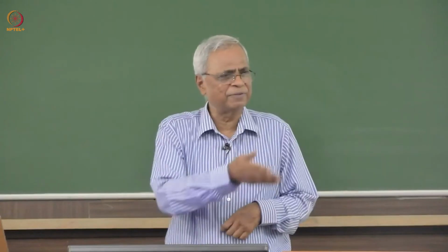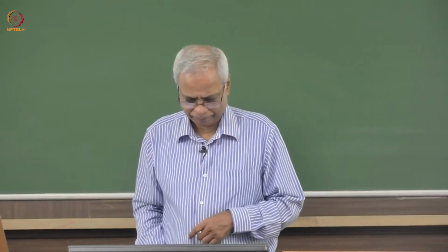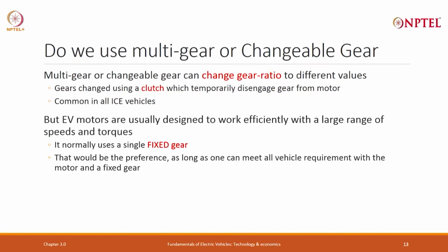If I redesign that vehicle, I will not put that. Single gear will be preferred, but sometimes vehicle requirement forces you to. But as motors become more and more powerful, you will see single gear will actually come up. I have repeatedly pointed out, power does not change except the efficiency factor is there. To that extent, power will get lost. We will take that.